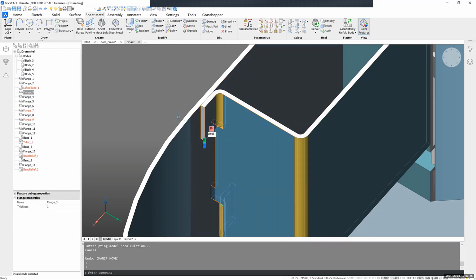You can select these two, and then you will see they're 10 or 10.05 apart. That's because the design intent said that we wanted this entire thing to be 12. And with the bend, this results in from this till this, it's 10. And now I want to constrain them together.